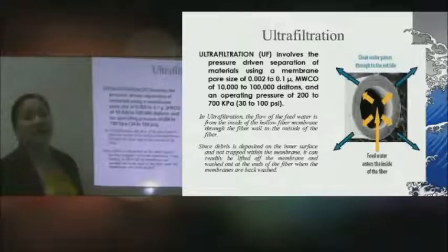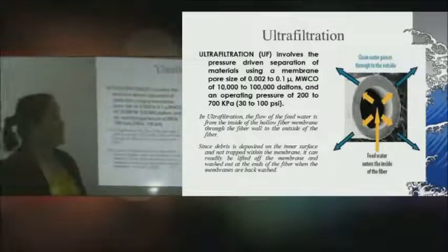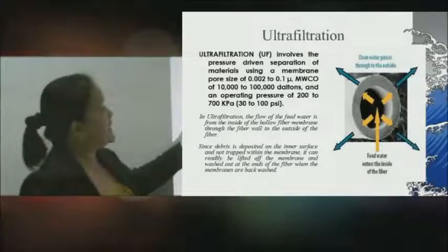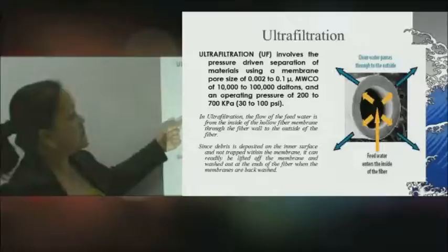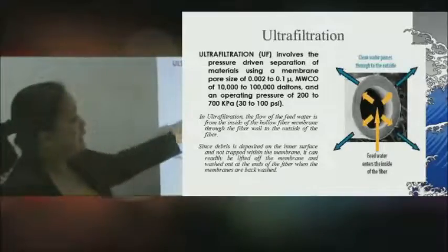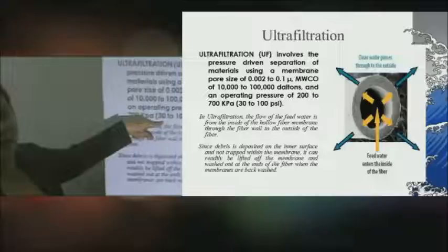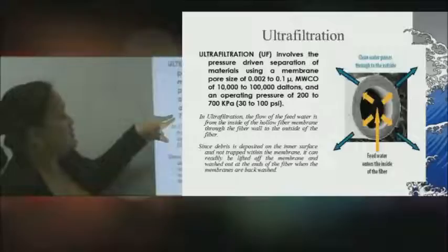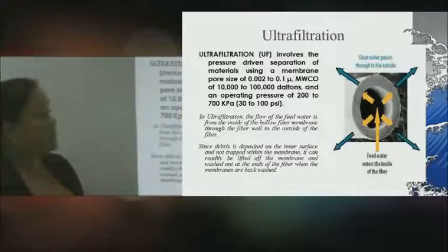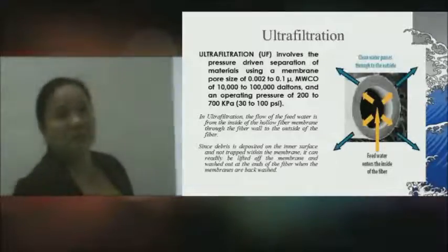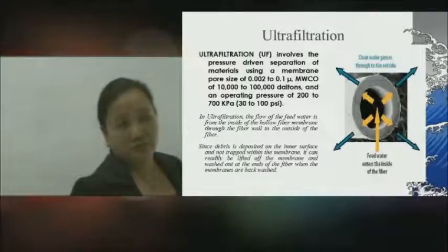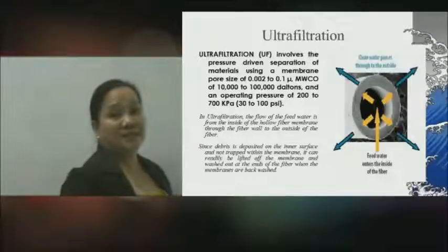However, again, this would give you an idea how costly it is to maintain such an ultrafiltration setup. Because take note, the ultrafiltration involves the pressure-driven separation of materials. Take note of how high a pressure you need to maintain: 200 to 700 kPa, or about 30 to 100 psi. This is only to maintain the ultrafiltration process, and does not yet include the maintenance of the filter.